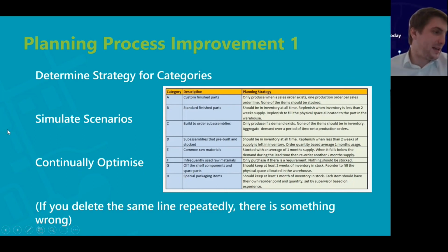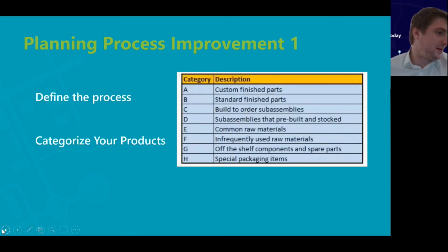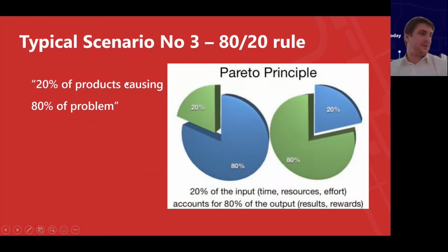As I was saying in a few screenshots before, there is a principle that 20% of products cause 80% of problems. So let's design categories in such a way that you run these problematic items only, let's say, once a week, once a month, or whatever the process requires, but completely isolate them by item category into different runs.